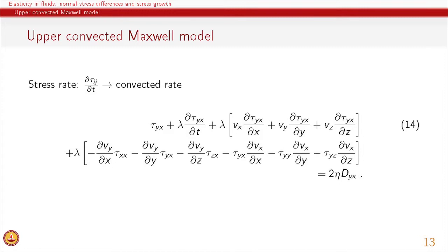It is only the terms due to deformation in the material which will contribute. For example, we are looking at Vx as a function of y, so this term will certainly be present, while Vx is not a function of z, so that goes to 0, and since Vy itself is 0, with flow only in the x direction, all these terms will drop out.